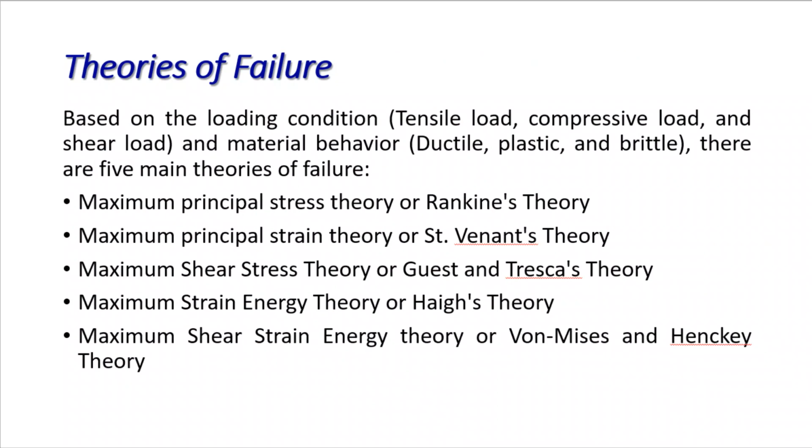And what are the theories of failure? Based on the loading condition, tensile load, compressive load, shear load, and material behavior like ductile, plastic, brittle, there are five main theories of failure. Maximum principal stress theory, also called Rankine theory. Maximum principal strain theory, also called Saint Venant's theory. Maximum shear stress theory or Tresca's theory, maximum strain energy theory or Haigh's theory, and maximum distortion energy theory or von Mises and Hencky theory.